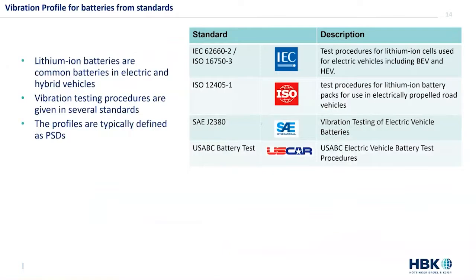Those are the ISO, SAE, IEC, and this US ABC battery test standard. They all refer to lithium-ion batteries, which are indeed commonly used in electric and hybrid vehicles, and they all contain vibration testing procedures, and these are typically defined as PSDs.